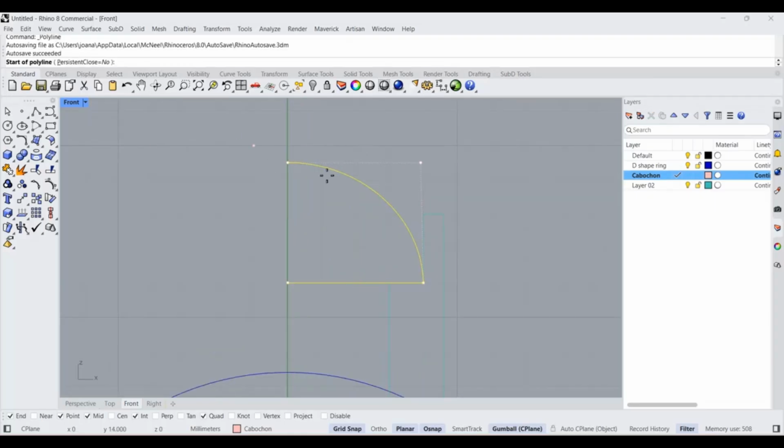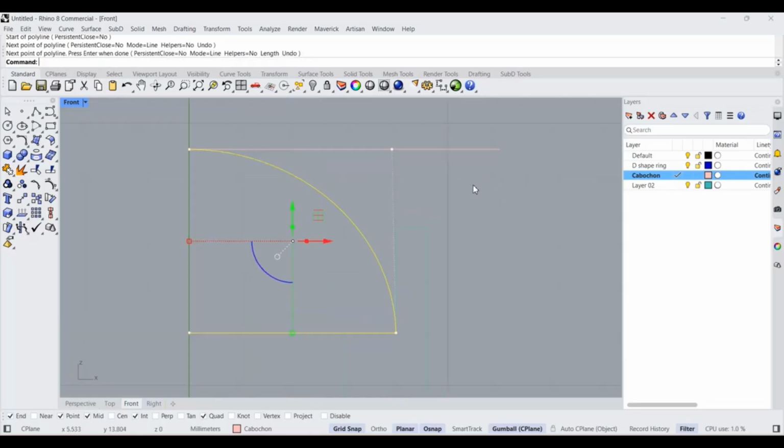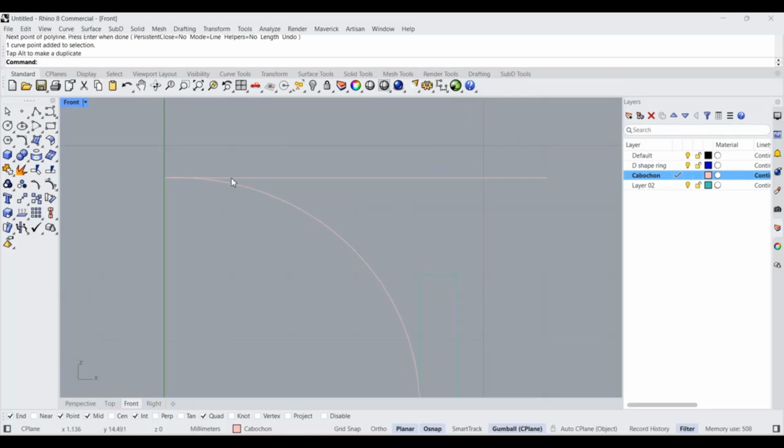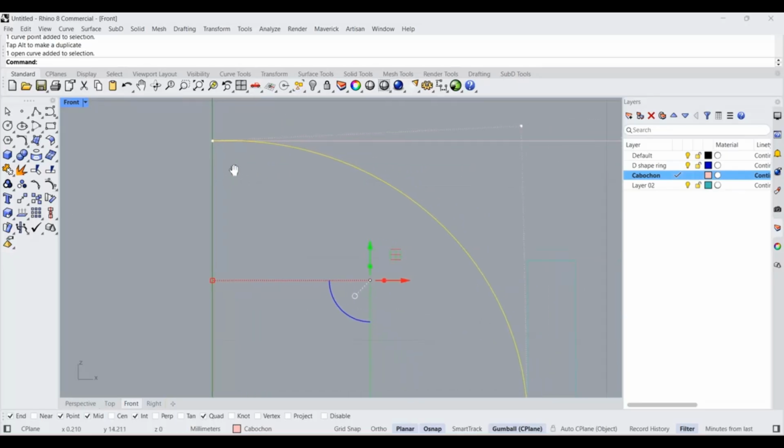If they are not aligned, imagine that this point was a little bit up, which probably my first curve was. If you're going to revolve or mirror it, you can see that this curve is lower here than here. So when you revolve it, you're going to have a dip in the middle, and you don't want that.